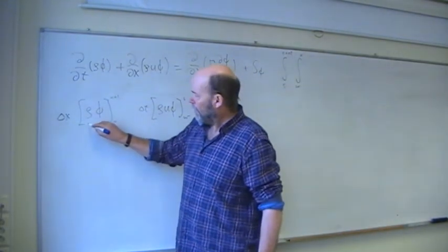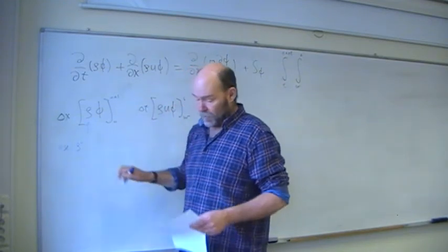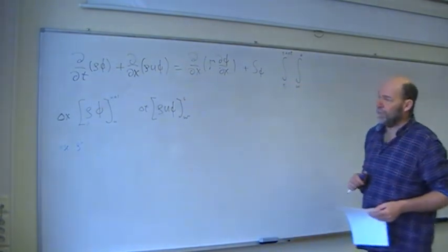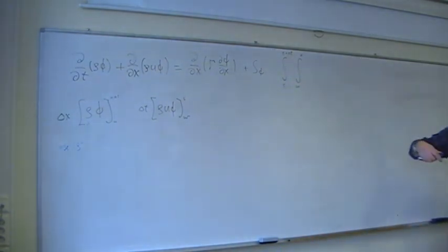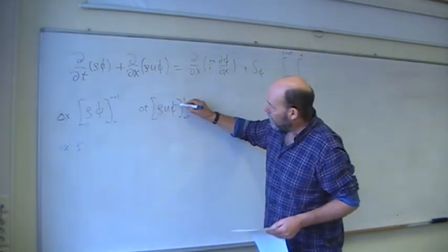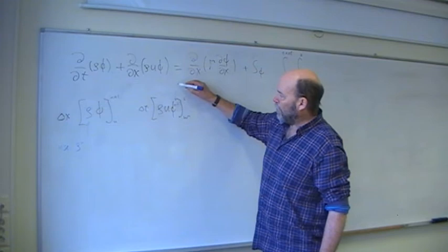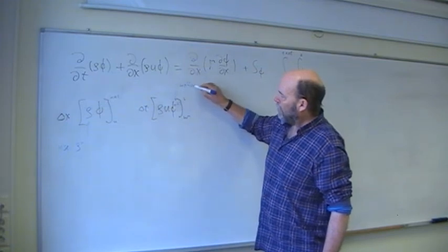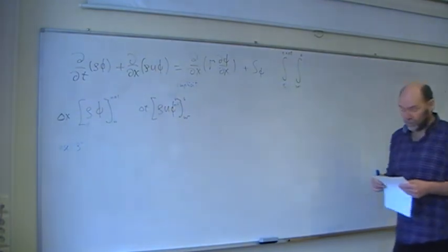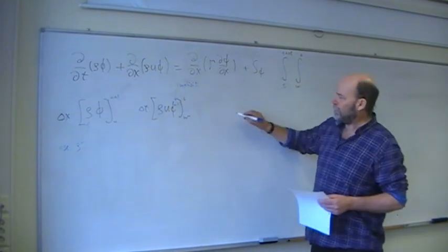Here you can stabilize a lot by using the old density instead of the new one at the new time level, at least the first time. You have to do this iteratively anyway, so you have to cheat a lot. Also, a stable trick, use n plus 1 here. So it will now be a little bit more implicit, which also tends to stabilize.